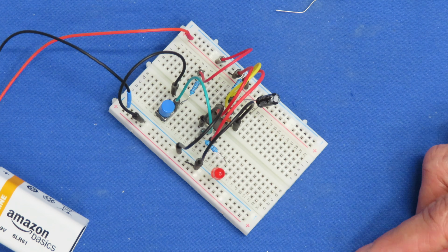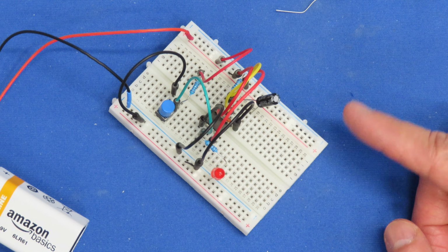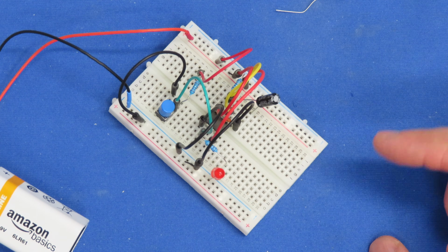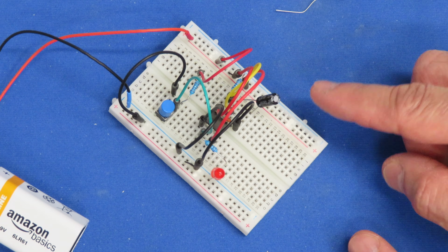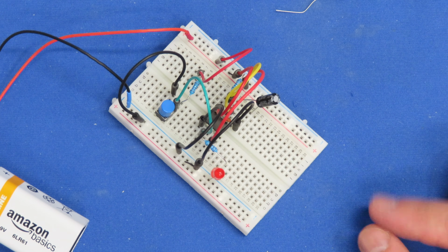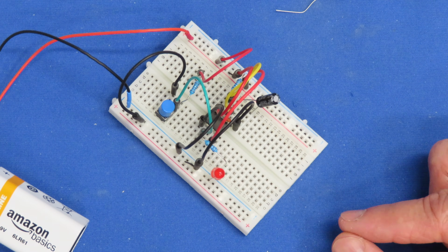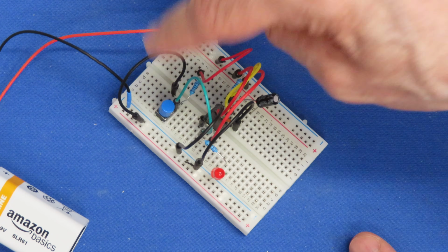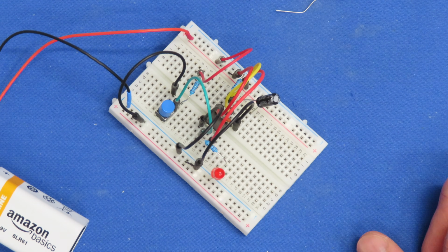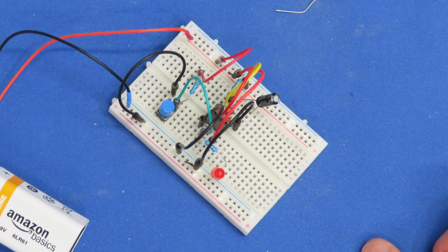And this is actually a very useful circuit. You could use this as the input for another device as a debouncing type of circuit. You wouldn't need to use as big a capacitor as we have over here, but one press of the push button is only going to produce one output pulse, even if there's a bit of noise on the push button. So it's a very useful application for the 555 timer.